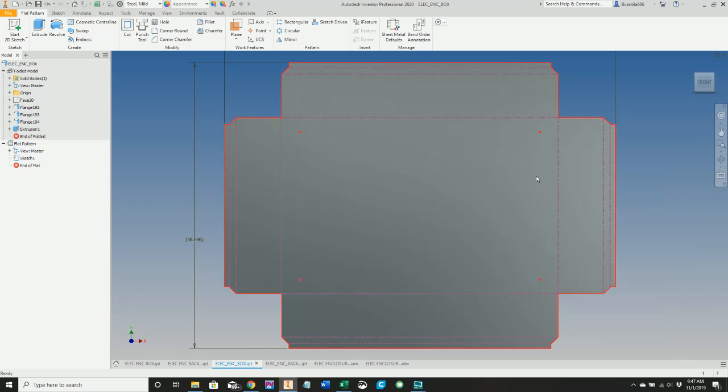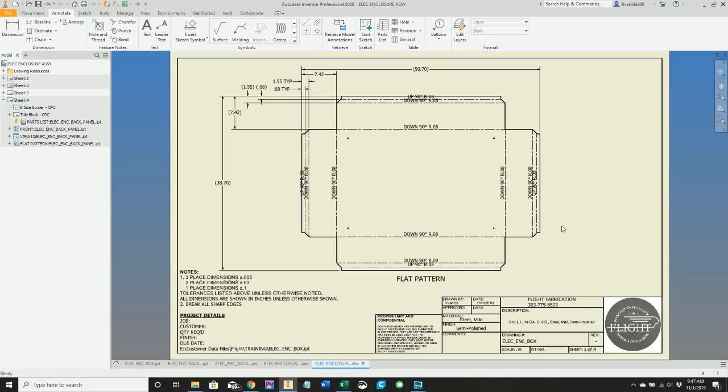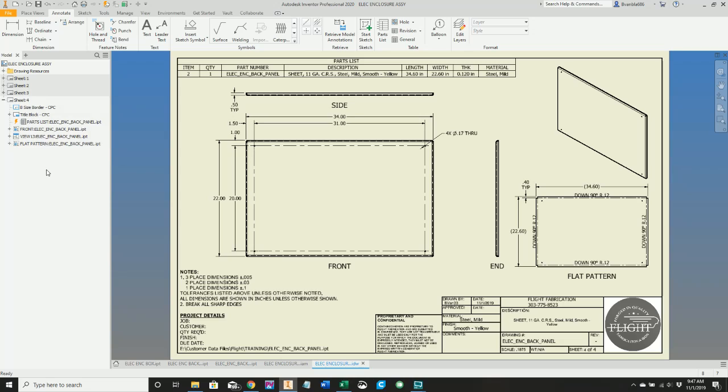That will ensure that whatever software they're using, regardless of whether or not it can accept a 2020 DXF or 2004, most of the programs out there, as long as they're fairly new, will be able to accept it. Lately, Derek has been having a lot of problems with being able to open anything from this new version. So just make sure that you save down your DXF files.